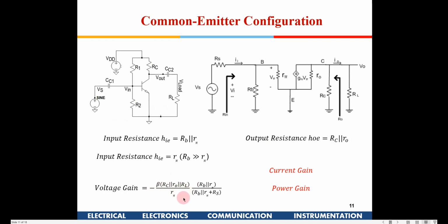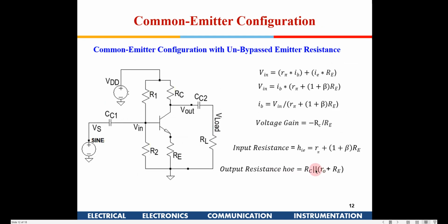So this amplifier is not suitable where we need voltage gain and RL is very low. These are some of the things you should know, which will help you choose the correct amplifier configuration. When we learn the other amplifiers also, we will come to know what kind of amplifier we need to choose in case RL is low. So that we will learn subsequently, right?